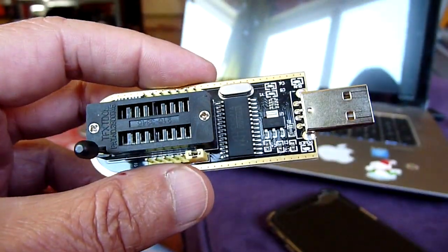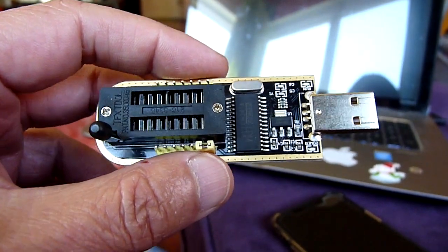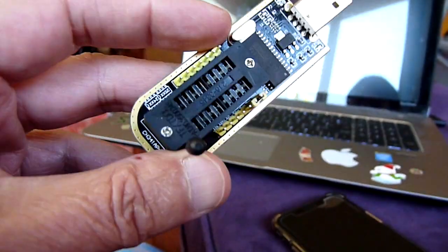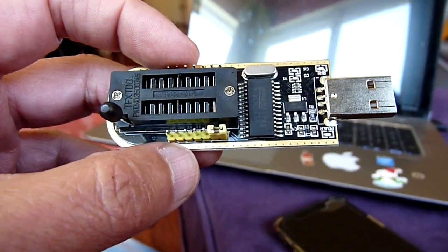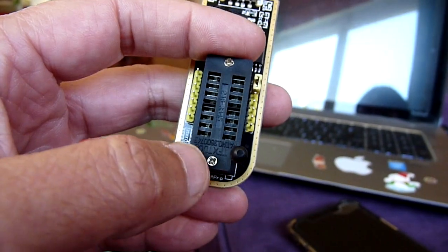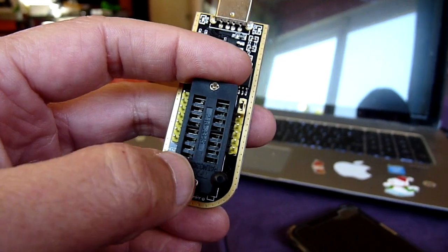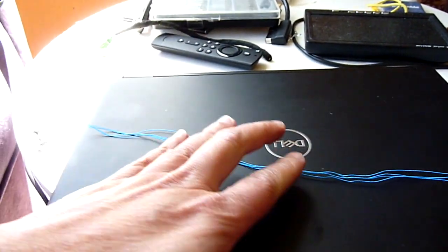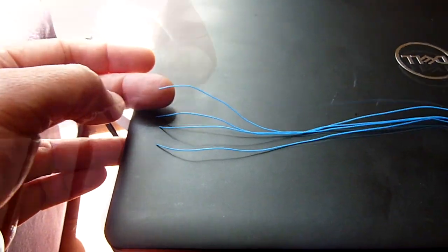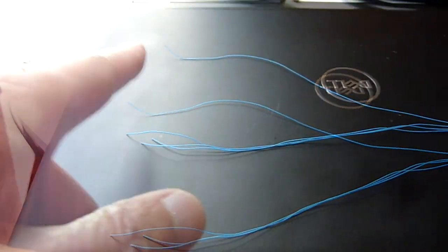Buy a USB CH341A programmer. So this one is for the 24 series and the 25 series EEPROM, or they call it I2C. The wiring is that you need to put all those 4 wires in here if you don't have a soldering iron. So here I'm going to show you how to put them. So you need 4 wires, and this one is called 30 gauge, which is very small, and you need to strip both sides.